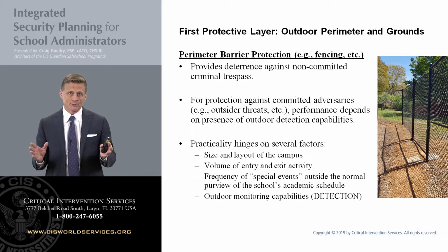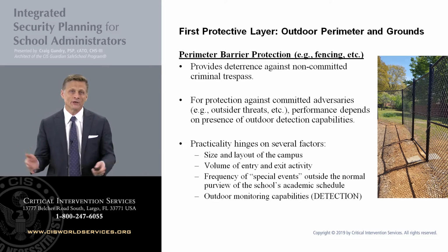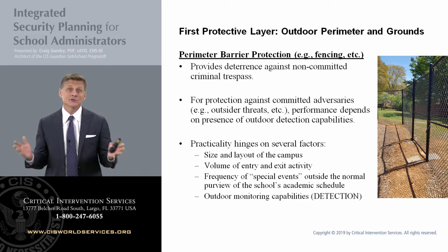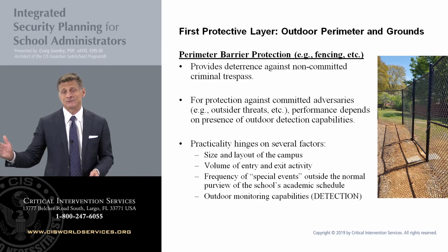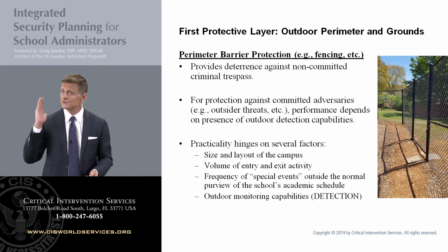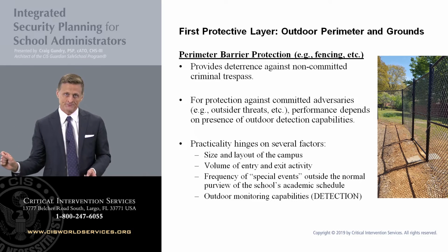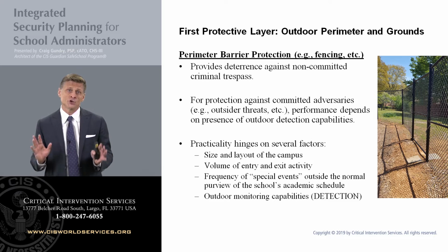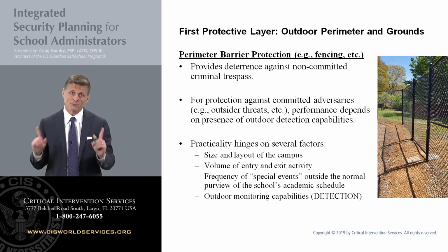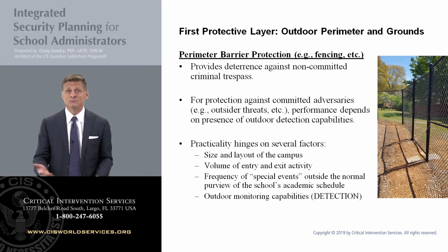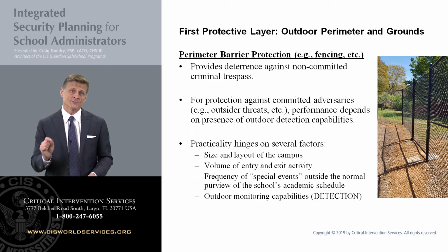What is a barrier, like a fence? Quite often when I ask that question of lay people, when dealing with clients, the answer that many people give is that it stops somebody from coming in. Well, a fence, and this is true for all barriers, walls, locks, doors, windows, all this stuff, a barrier does not stop anybody from doing anything. All it does is delay them from doing it. Good example, a 7-foot-tall chain link fence attached to a bottom rail with a barbed wire top guard, according to Sandia National Laboratories, only has a mean delay time of 8 seconds against an adversary with gloves. That is its true performance measure in a performance-based physical protection system.